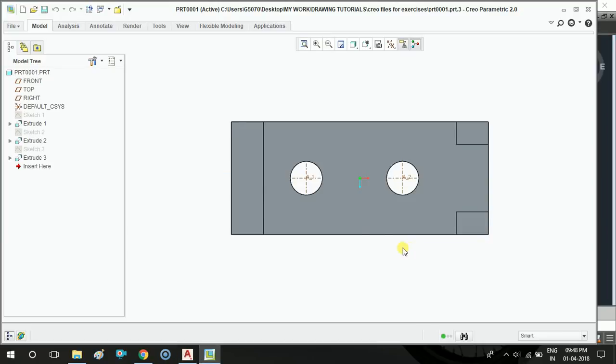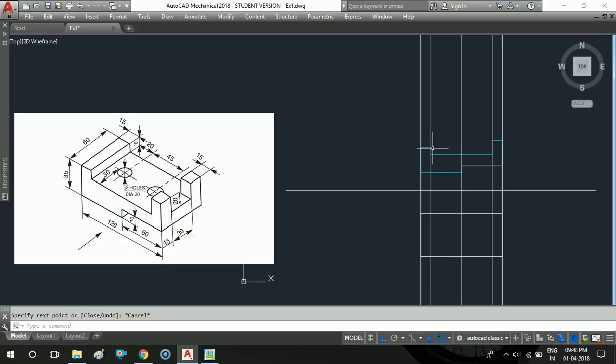Next we can see one line related to the step which is of height 10. Already we have drawn a construction line, so on the same line try to draw another line with the HB pencil. Next, similarly, we can see two squares here, with a dimensional value of 15 mm. Go for line. The range is already given, so start from here and click on the corner we got, and now give the dimensional value, up to 15 mm. Next, similarly, directly join it to the extreme position. Similarly, we initiate one more square from another corner, with side 15, and here also 15, and here also directly join.